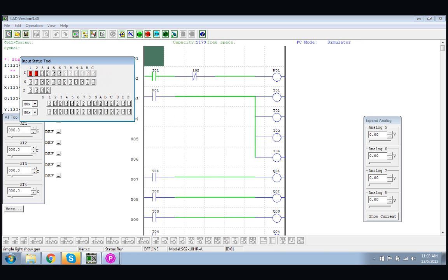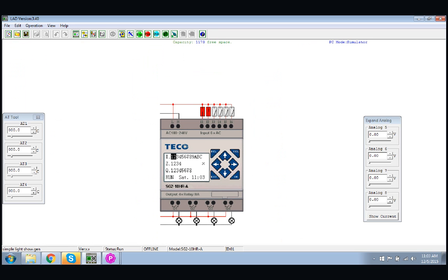Basically there's an unlimited number of options with the timers, the counters, the internal relays, and I've actually programmed a couple of these for actual applications in the field. Two of them that I know of, we programmed them, set them up, and as far as I know, they're still running. One's on a machine that sews bags in a plant. Once the bag is filled with seed, it runs across on the line to the sewing machine, and it's this TICO unit that's using photo eyes to detect whether the bag's present or not, and if it is, then it activates the sewing machine head.